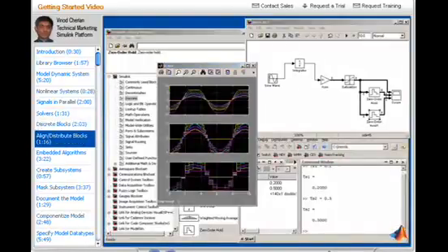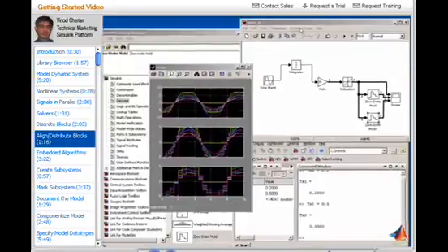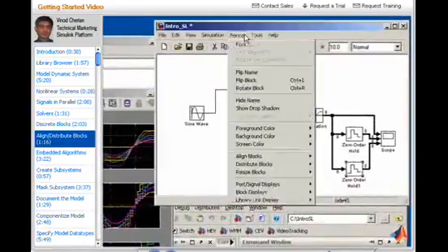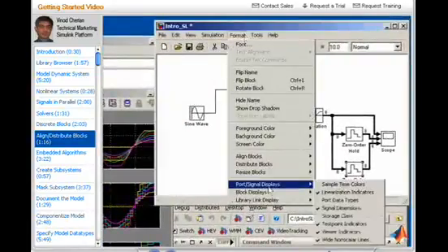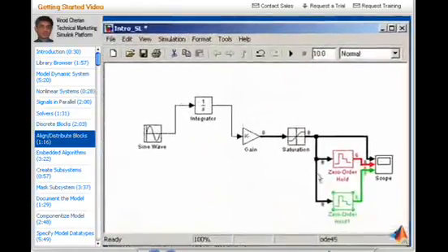Now in this system, Simulink also provides easy ways to visualize which of the signals are continuous and which of these are sampled. So I just turned on the sample time colors, and you can see the black lines in the black blocks represent the continuous parts of the system, the red lines represent the fastest sample signals, the green lines in the green blocks represent the next fastest sample signals, and so on and so forth.